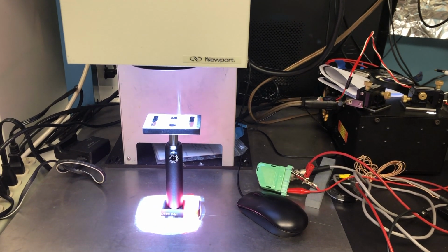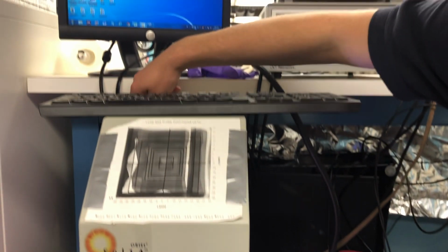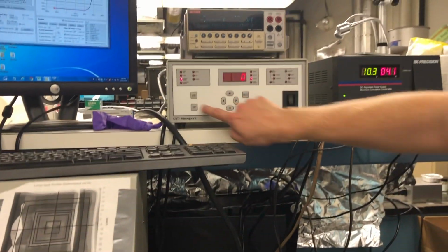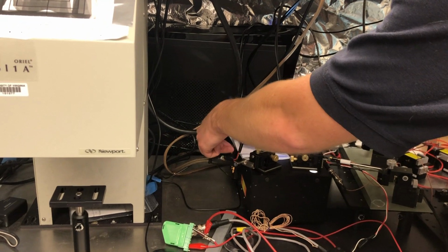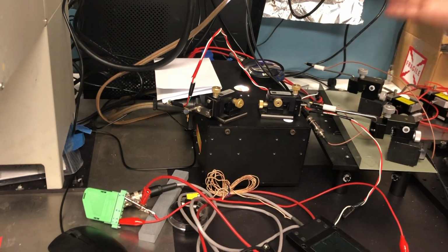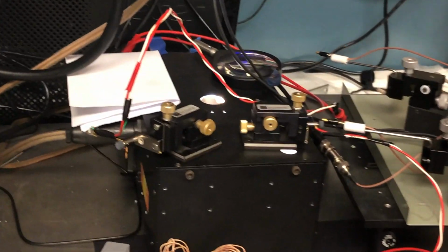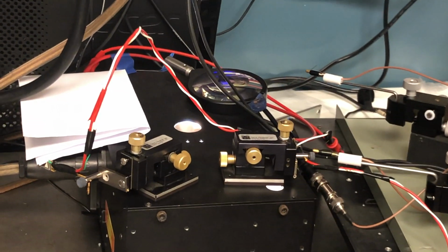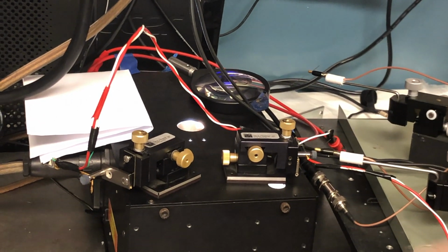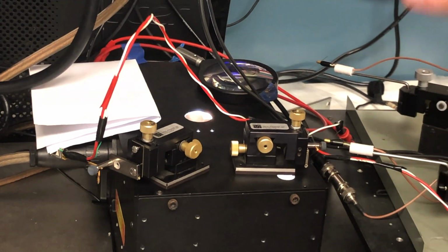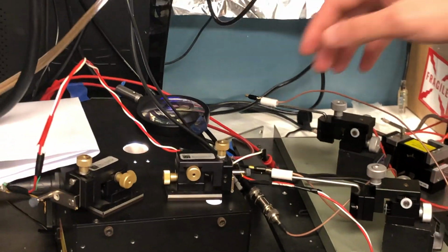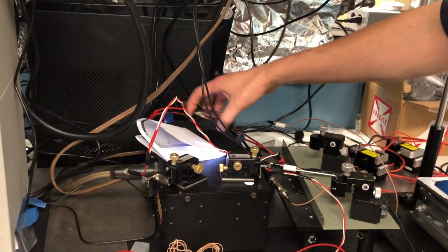With some more modern cells like IBC cells, it's better to use a lamp where the light source comes from the bottom, and that's what we have here. Since the light comes from the bottom, you would place your cell face down, and then put the probes on the back for all back contacted or IBC cells, and that's just so that it's easier for you to move the probes, and your cell still gets all the light. So those are our lamps.